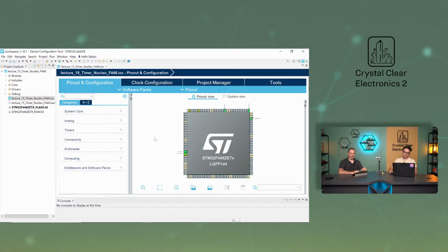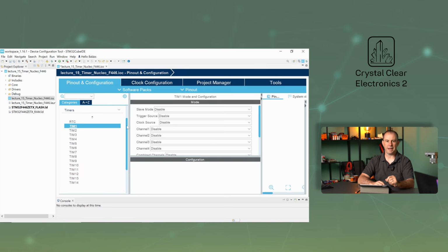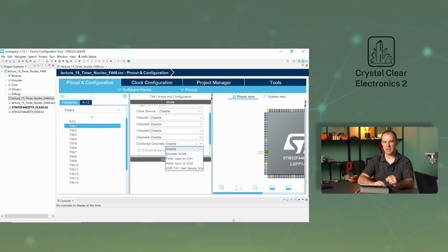In that chapter, you will also need to know how to configure it, so let's take a look at what settings you can work with, as we did in previous modes. First of all, in encoder interface mode, we need to set which input we are working with. In general, you can use only A, only B, or both A and B. Of course, these signals must be tied to the appropriate legs of our counter and timer module. You can set the 2-input mode for TIM1, for example, by selecting encoder mode in the Combined Channels field.